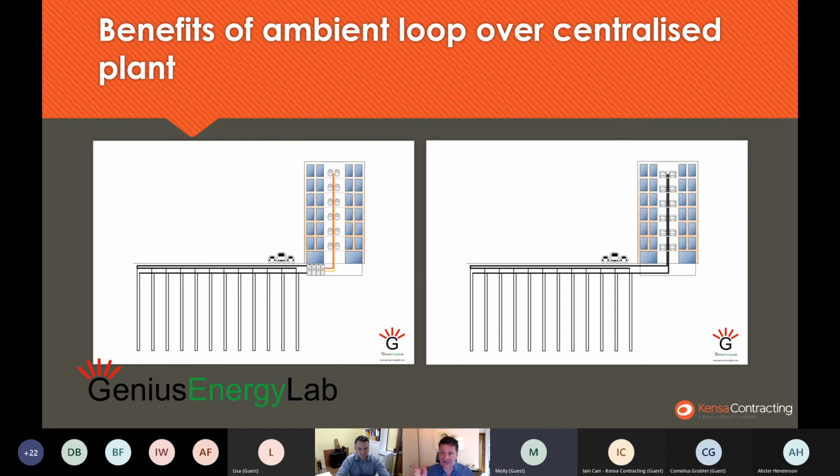So again, you can select the heat pump to suit. Other points to note are overheating in corridors where these pipe runs come up is a real problem in these systems, because they've got to run that network all year round at 65 degrees to deliver that domestic hot water. So the losses into the corridors can be quite a problem for them. So lots of benefits technically to the distributed heat pump solution.